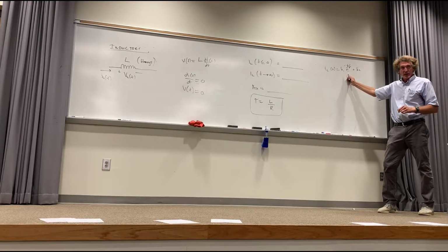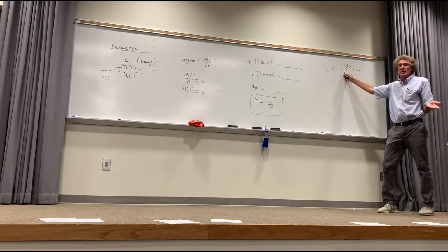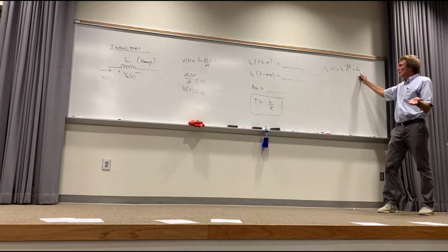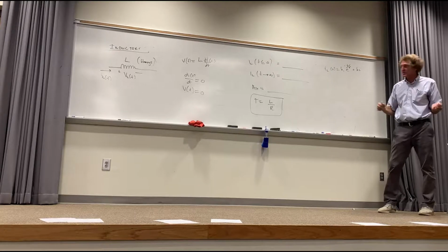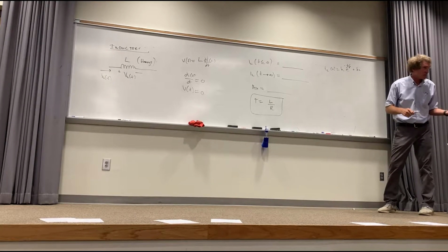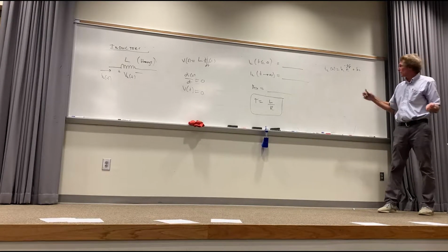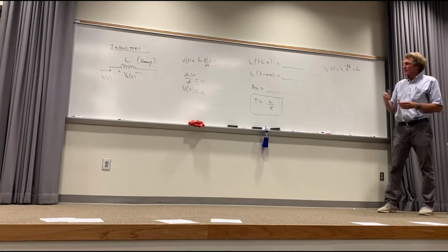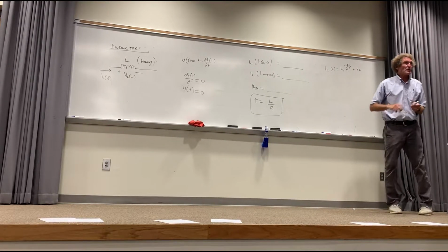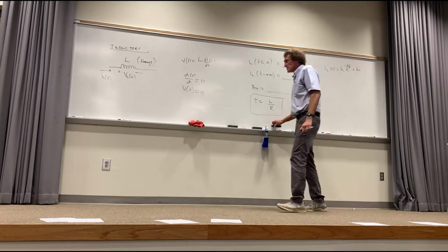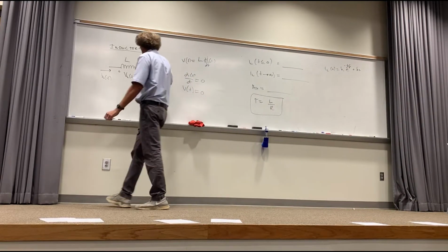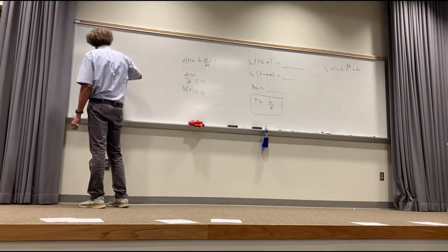Following? Now, the current at t equals 0 is not equal to K1. It's equal to K1 plus K2, because at t equals 0, e to the 0 is 1. A common mistake is they'll just put in that current there. It's wrong in general if there is a current at t equals infinity. The time constant is the critical thing. Now I'm going to do several problems related to this to expose how you do these things. It's really through working problems you get an understanding of this stuff, in my opinion.